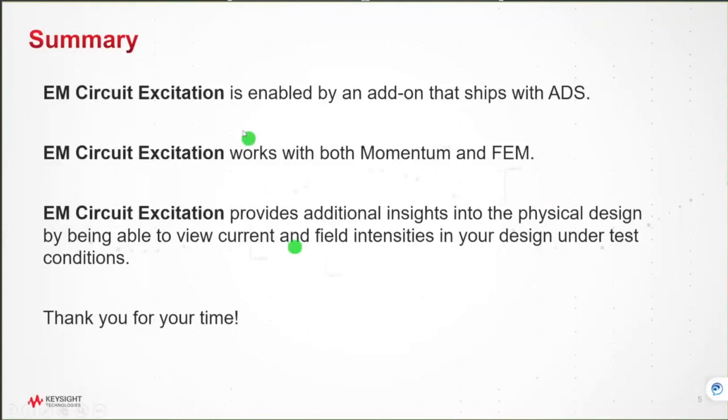Okay, so those are the examples, the demos to run. So quick summary. The EM Circuit Excitation is enabled by an add-on that ships with ADS. Pretty easy to get in there and turn that on. It works with both momentum and FEM. And this allows you to have additional levels of insight into your design by being able to look at the visualization of the currents and the field intensities with the component models in place and under full drive conditions. And that's it. Thank you for your time.